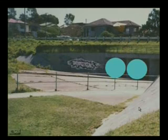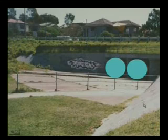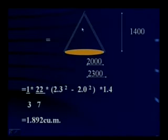For the purpose of calculation of quantity, we assume that these slopes are 1/4 of a cone. You just cut a cone into 4 parts. Each corner would make 1/4 of a cone. Okay, this is how it is. See here, there are 4 quarters of a cone. So when we add all these, it comes to a single cone.